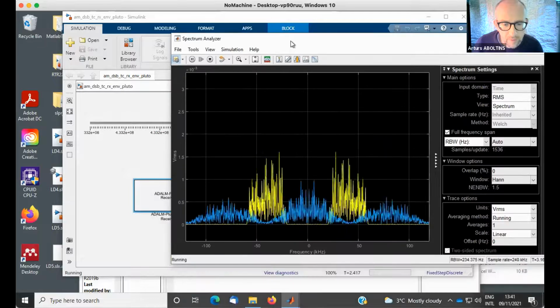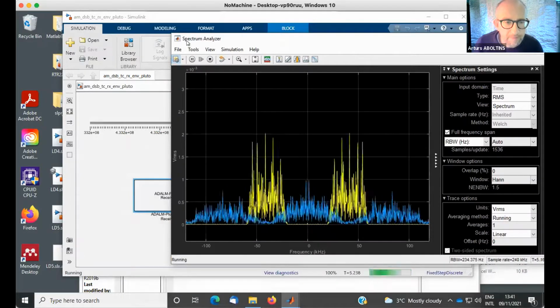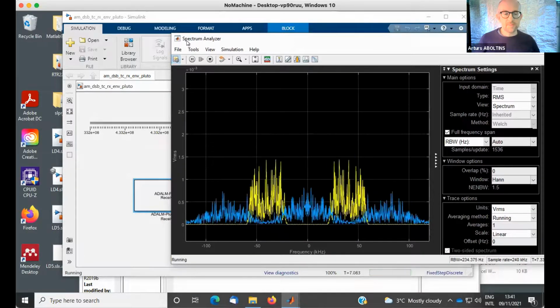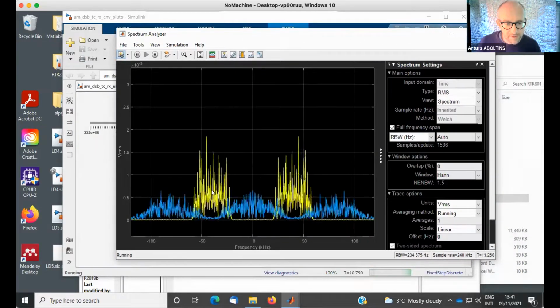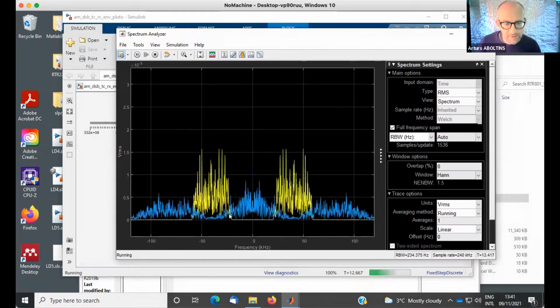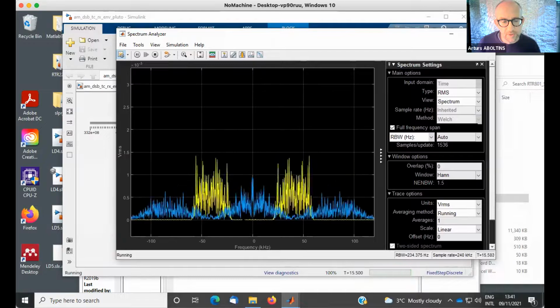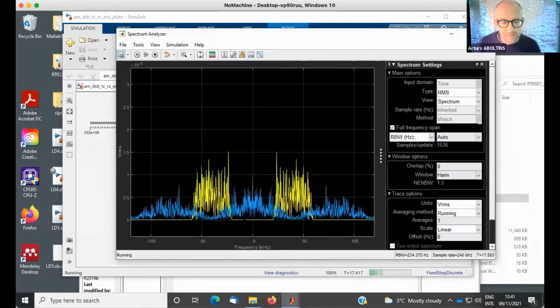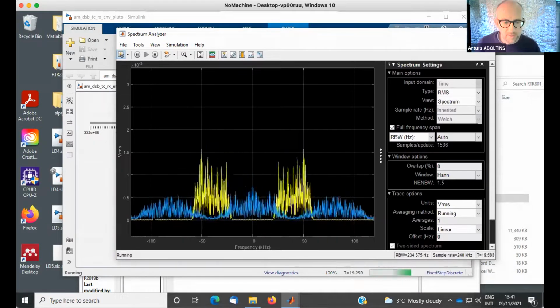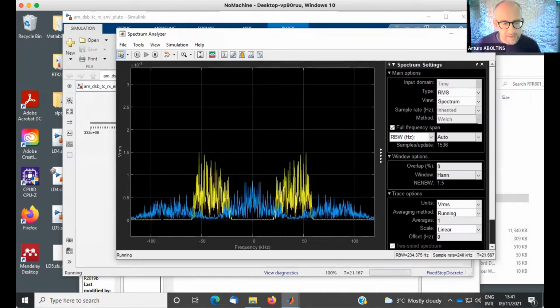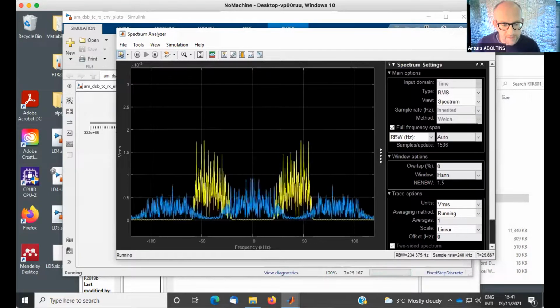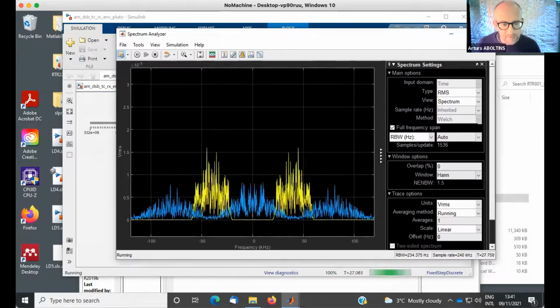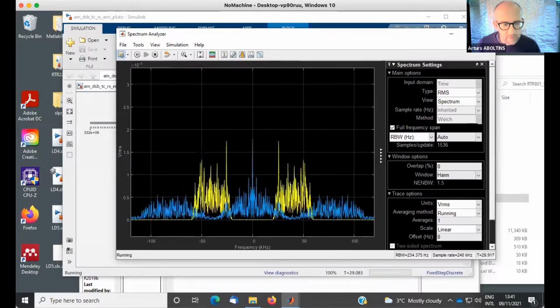Okay, now, of course, because we do not have a transmitter, this is just noise which is amplified by the filter. This is what I was talking about in the beginning of the lecture, when I was drawing that the filter cuts everything outside this band where it's amplified. So it has like 40 kilohertz bandwidth, and it's centered exactly at 40 kilohertz.